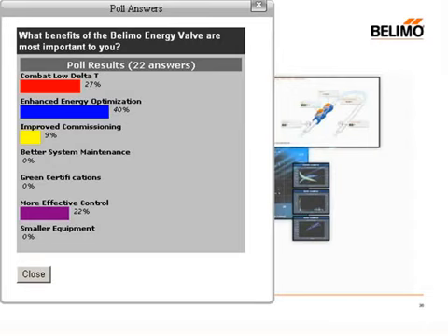It doesn't have to be cleaned out. Same type of situation with the temperature sensors. The ball valve is a characterized ball valve, so there's a self-cleaning property within the valve itself as it turns on the seat. So no, there's no calibration required for these.